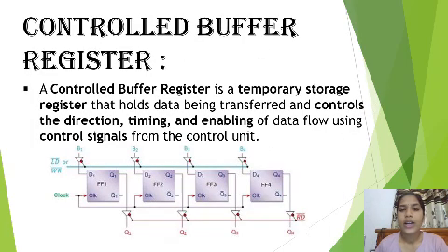Second one, controlled buffer register. A controlled buffer register is a temporary storage register that holds the data being transferred and controls the direction, timing, and enabling of data flow using control signals from the control unit.